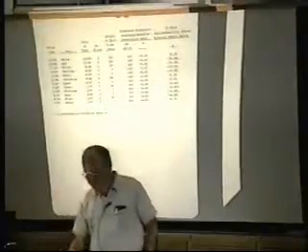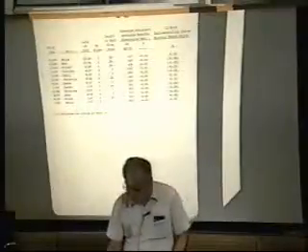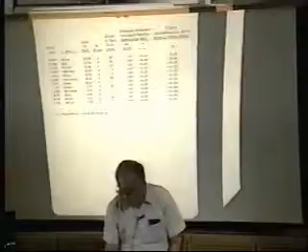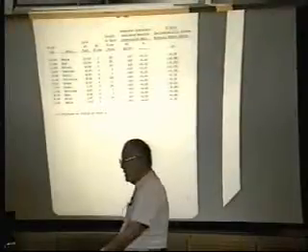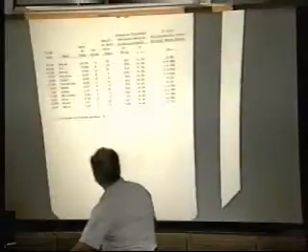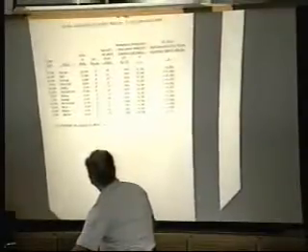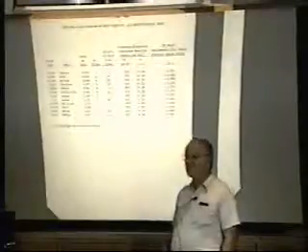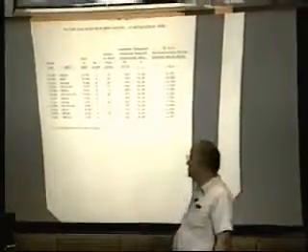We had flow after flow tests. I'll show that next. We had flow after flow tests on each of these wells. We had a policy in the gas department: whenever a well was completed, it was multi-point tested after it was cleaned up.